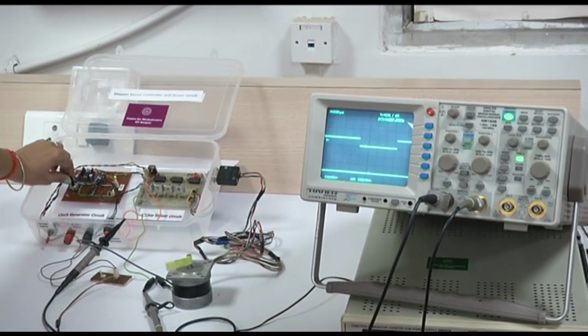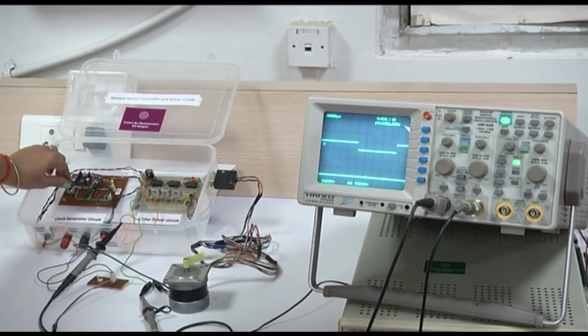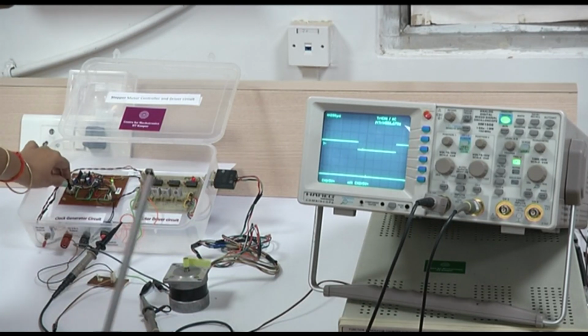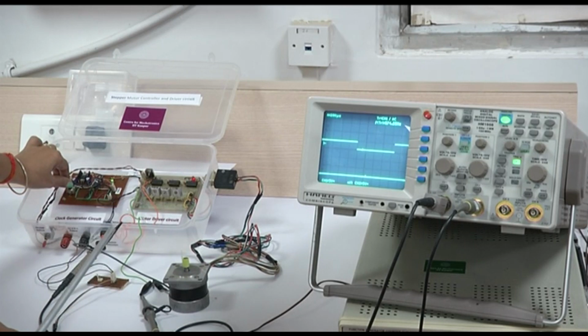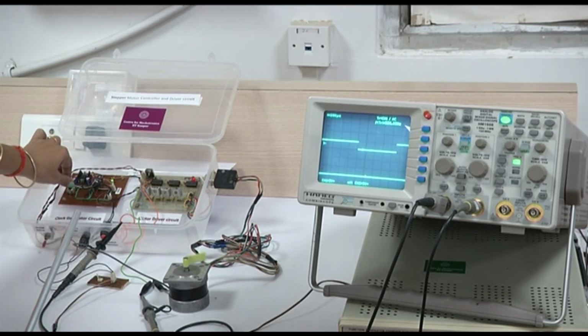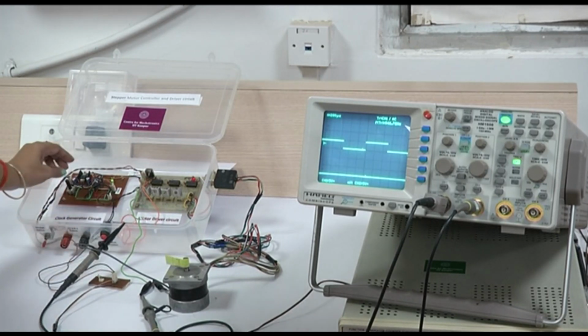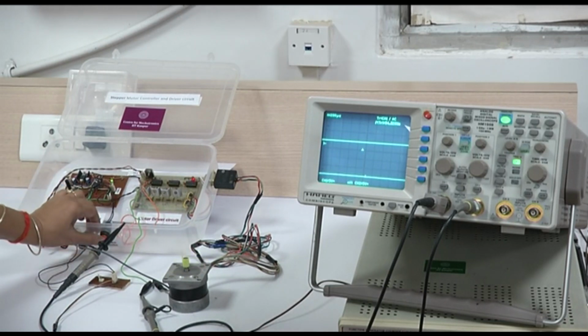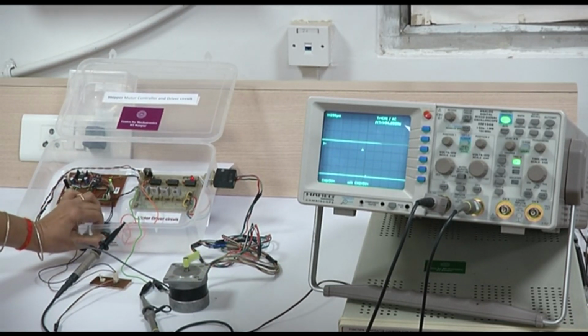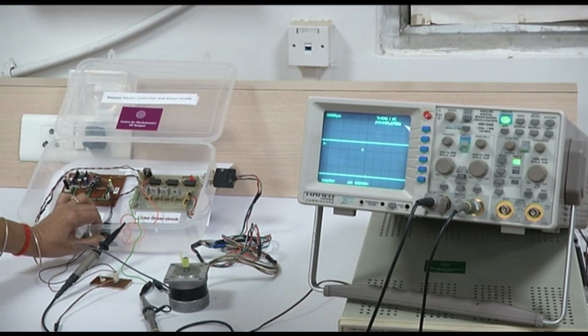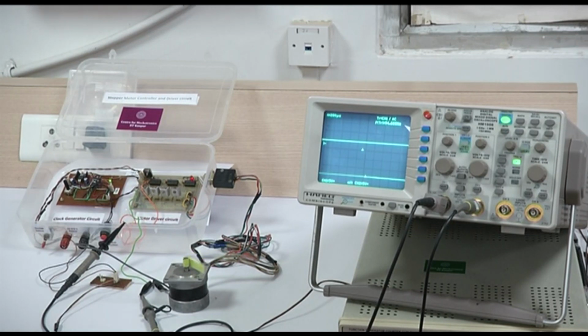Here, it does not respond correctly. So, the switching time we can say is around the hundreds of microseconds for this inductive load of this motor. So, this is the simplest circuit. We can change the direction of the motor by changing the direction bit. So, this is the simplest control and drive of the stepper motor.